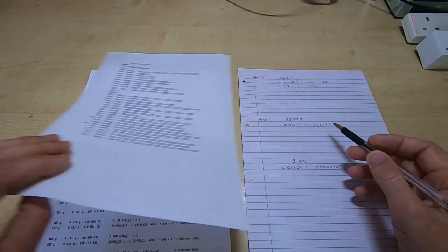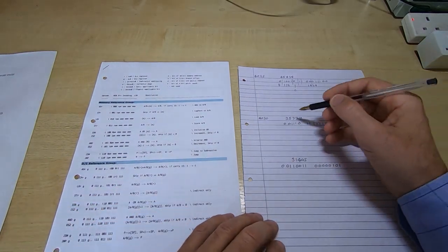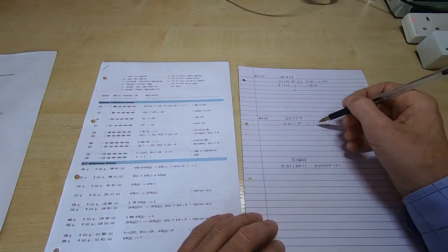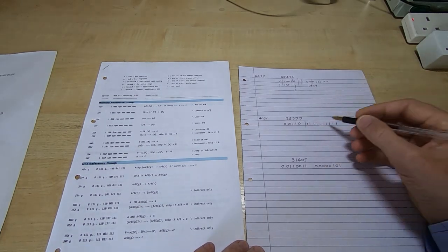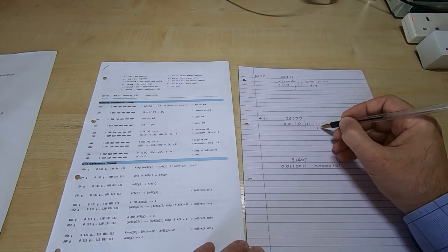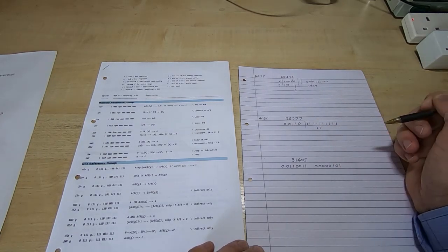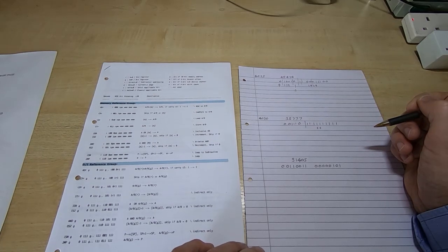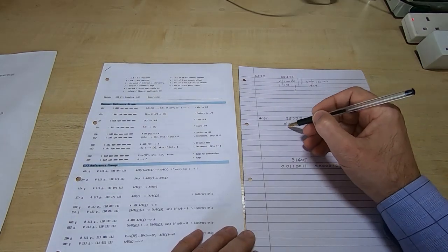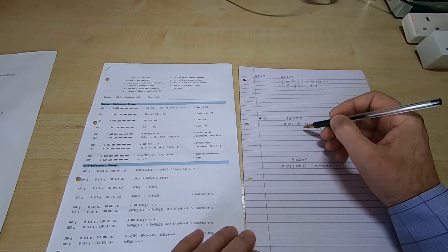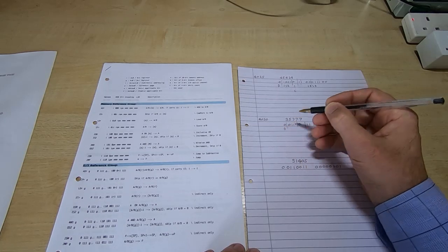Okay, so what we'll do now is decode the next instruction. So this is the value that we captured, and if we do the same thing, the first 10 bits are again the address, so that is FF, which is a bit alarming in itself. We shouldn't really be looking at an address like that within the code. And then if we decode the instruction again, it's basically in 3 parts. Firstly, again, we're looking at direct addressing.